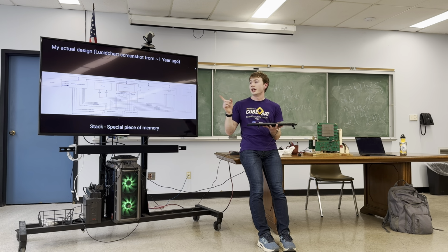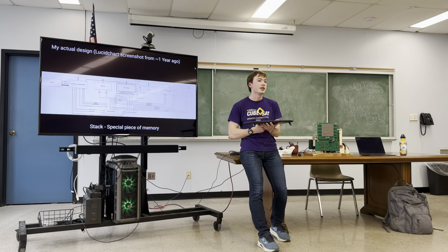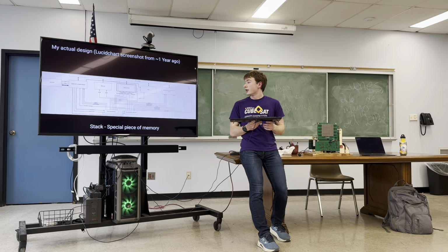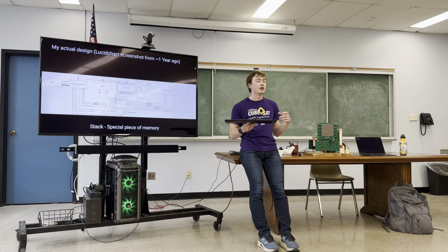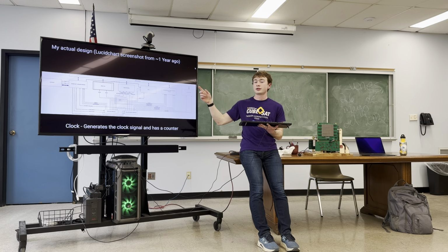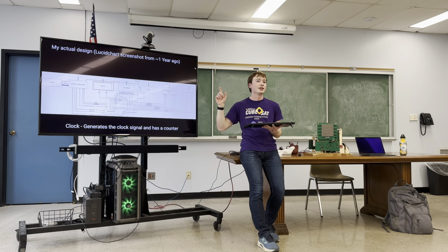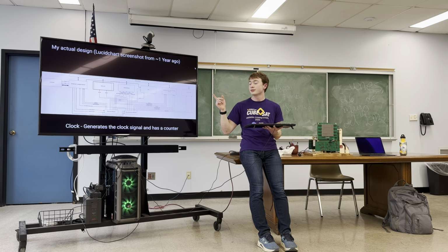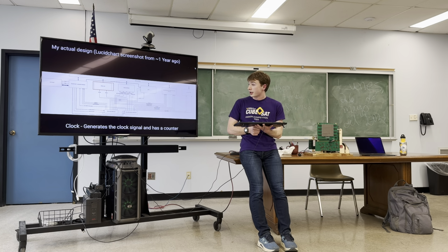And I made it a bit more complicated so that you can reach down from the top and access data further down. It's used to store local variables and functions, and it's a lot more restricted than the general purpose RAM, which would also be called the heap memory in actual operating systems. And then this is the part with the clock. In the diagram I showed earlier, with the baton signal being passed around, there has to be a clock connected to all the timing logic to make sure everything steps in the correct way and at the right speed.